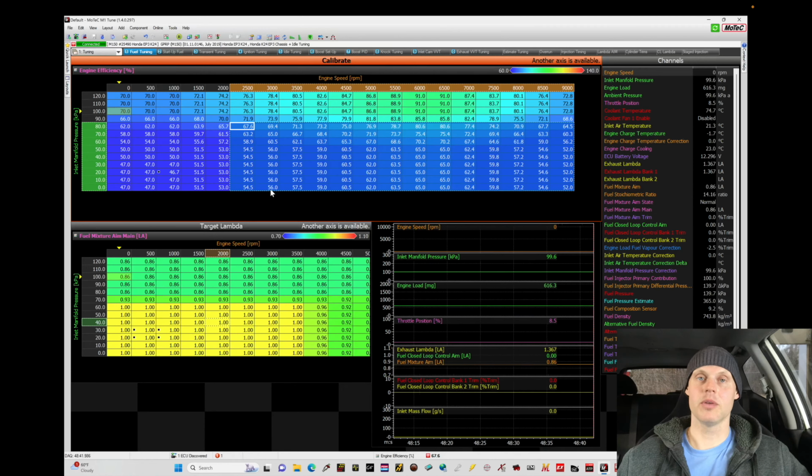And then finally, we're going to be looking and talking about how to set up our variable valve timing control so that we have proper variable valve timing in part throttle conditions for a Honda K series engine. We're actually going to take a look at that first in order to get all that configured and set up, so that when we're doing our actual part throttle tuning in the volumetric efficiency table, we don't have to worry about going back in and dialing in the volumetric efficiency table after variable cam changes.